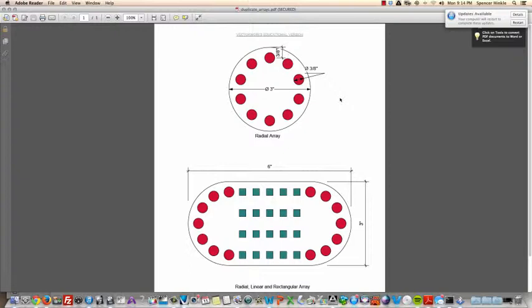Well, you don't want to draw each one individually. What you want to do is draw one station and then figure out what the spacing is in the x-axis and in the y-axis, and then you can do a duplicate array and say, I need 5 columns and I need 6 rows, and they have to be so far apart in the x-axis and so far apart in the y-axis, and you press the button and presto, they're all there. So that's what a duplicate array is.